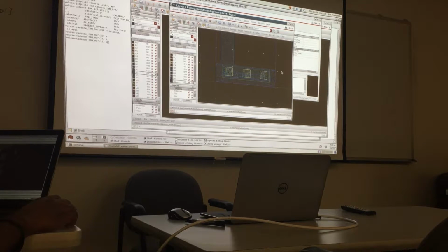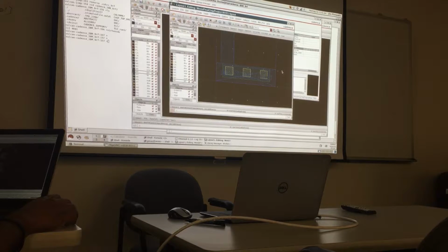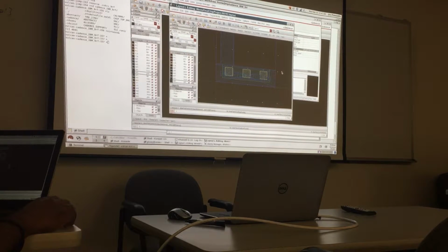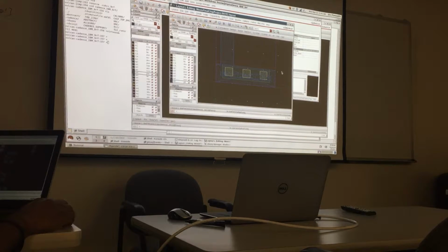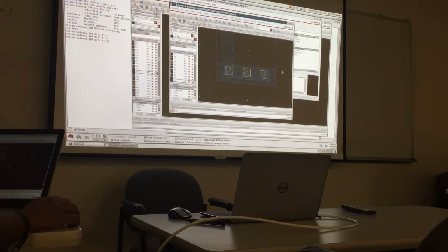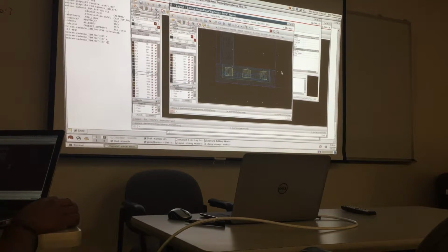Okay. Layer purpose, what's under that? Just label? Label, this label. Yeah, they made it kind of easier. Okay, I agree. So that's what you want. You want metal one, the purpose is label. And M1 is selected. No, you need M1 pin. M1 pin. Okay. Right, yeah, that's a common mistake.